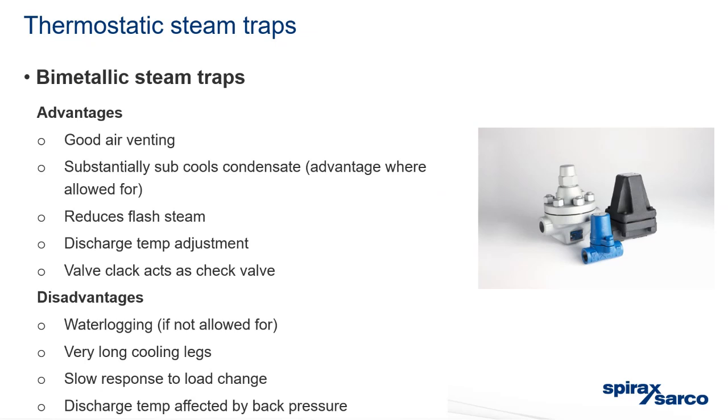Do we have any questions on thermostatic steam traps? Yes, well, steam traps in general more, I would say, but what if the line is more than 100 meters long? Is there a minimum distance needed between traps, or do you need to install where there's a change in vertical direction? I think you will handle that a little bit later as well. Yeah, I'm not sure if we touch on that in this one because I think we spoke on the installation one, but just as a general rule, we recommend steam traps every 30 to 50 meters. So if you've got a steam line that's 100 meters long, you would need at least sort of 3 trap sets, maybe 2.